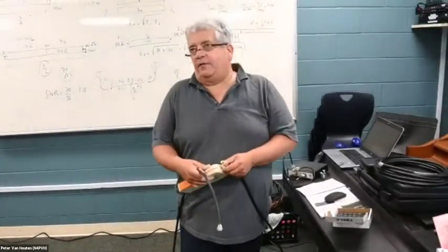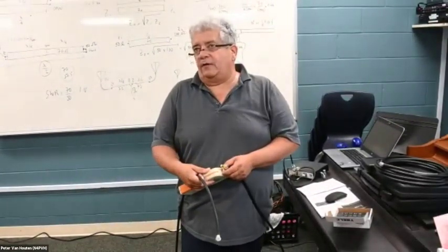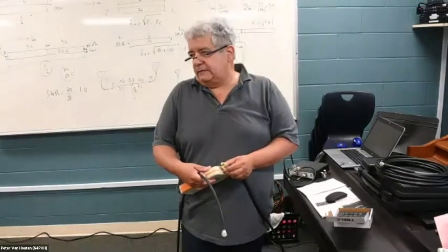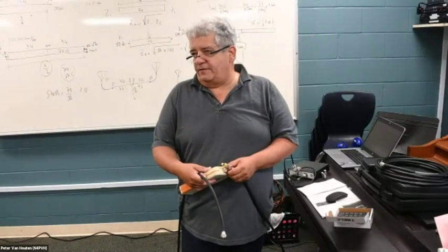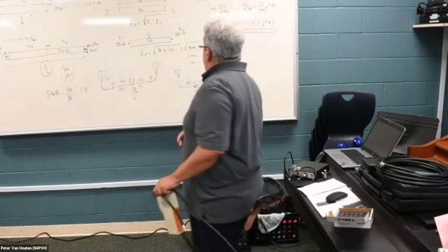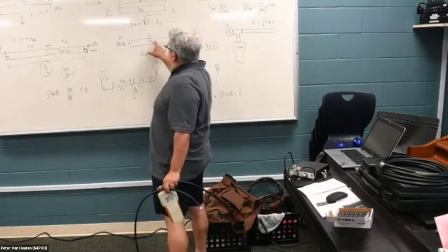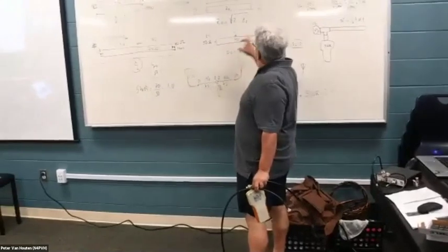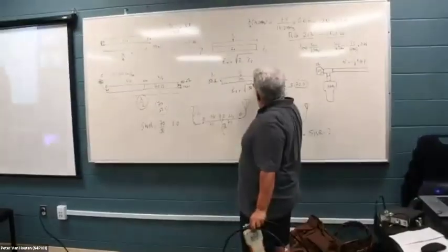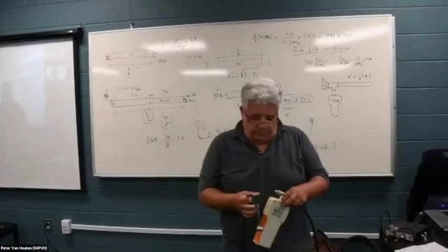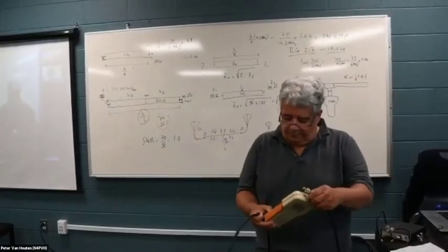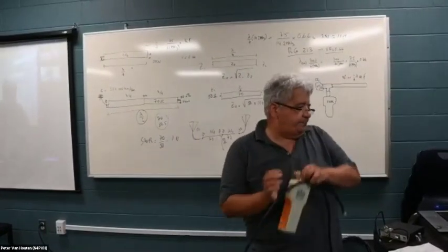And this is useful, for example, to match a quad antenna, which has like 100 ohms. Match it with a 75 or 70 ohm transmission line. Get the quad impedance closer to 50 ohms, and have a decent SWR.